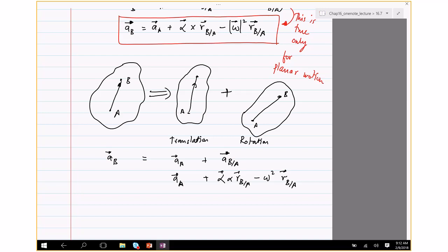When you solve problems of this nature, when you have a formula, again, there are two ways to do it. I talked about this when we did vectors. One is you try to write acceleration of B as a vector in i and j, same for acceleration of A, and same for everything on the right side. So when you equate the left-hand side to the right-hand side, you have components in i, you have components in j. From those two equations, you can solve for typically two unknowns.